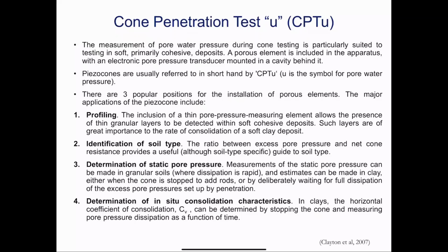You can also get static pore pressure. So if you want to know what's the in situ pore pressure, it could be in excess, could be hydrostatic. You just hold the probe there, as I mentioned, and you can deliberately wait for pore pressures to dissipate. When you push the cone in the ground, you will generate excess pore pressures. And if you wait for it to dissipate, you can treat this like a permeability measurement, or you can treat it like an oedometer or consolidation related parameters. Essentially, you can get the coefficient of consolidation. So that's the essence of a CPTU and the advantage of it.